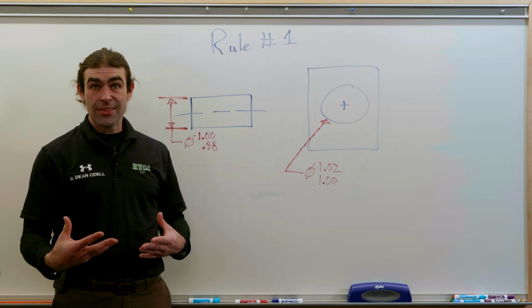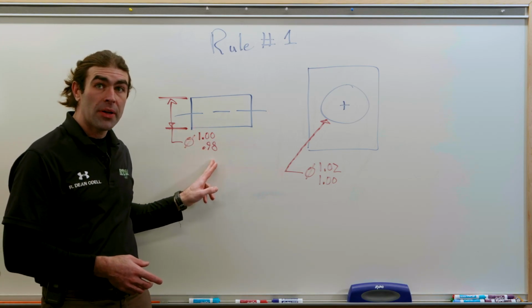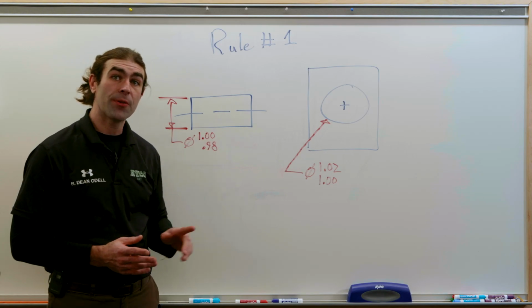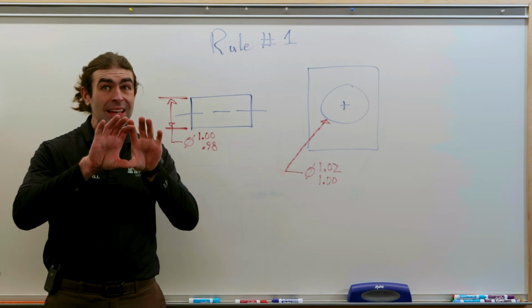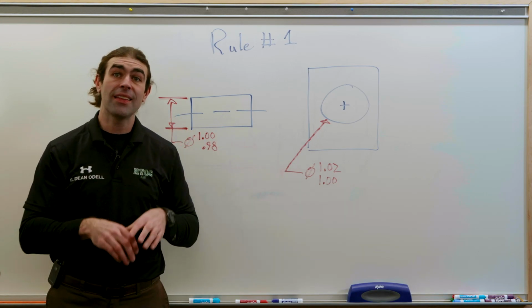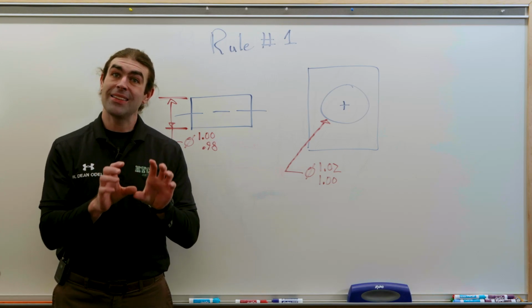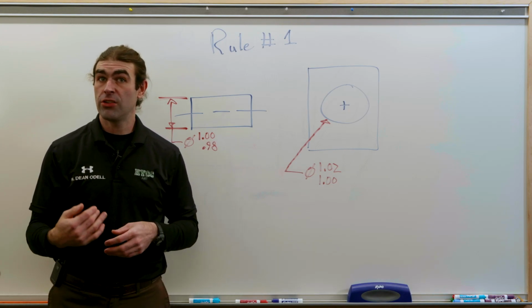Now, the next thing, there is no requirement for perfect form at LMC. So if the pin comes in at 0.98, it's allowed to be bent a little bit. So think about the pin fitting in that gauge. If the pin comes in small, it can be bent and still fit through the gauge just fine.